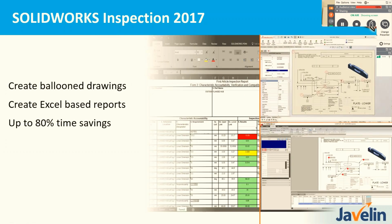So what does inspection do for us? I explained that it does balloon our drawings, but it goes a step further. When you balloon your drawings, it's not just a balloon and that's it, it's done. It actually pulls all that characteristic information. So if I'm ballooning a dimension, for instance, maybe a 3-inch dimension somewhere on my drawings, it'll pull that 3-inch dimension, and then give you your upper limit and lower limit and all those different characteristics, which we'll go through with the software.